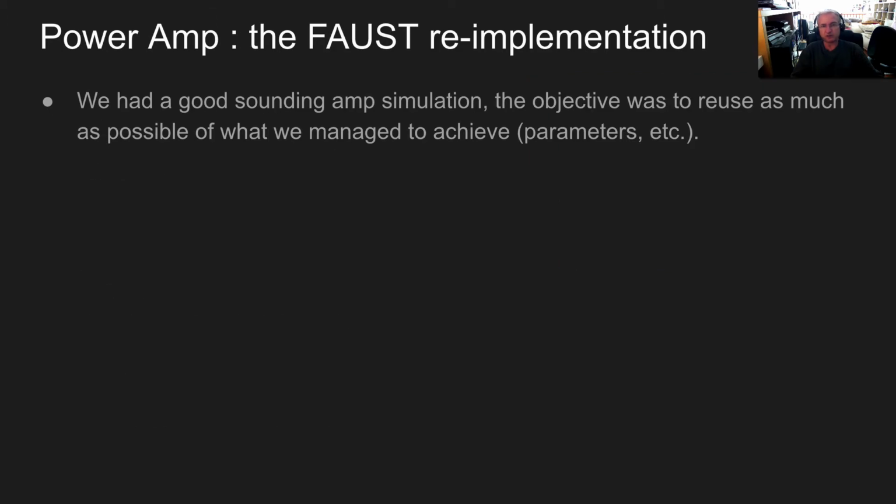Let's talk now about the FAUST reimplementation. So we had a good sounding amp simulation that has been tested by professional guitar players, was used in DAWs and so on. So the objective was to improve it using FAUST, but we would like to reuse as many parameters that have been fine-tuned during these years as possible.